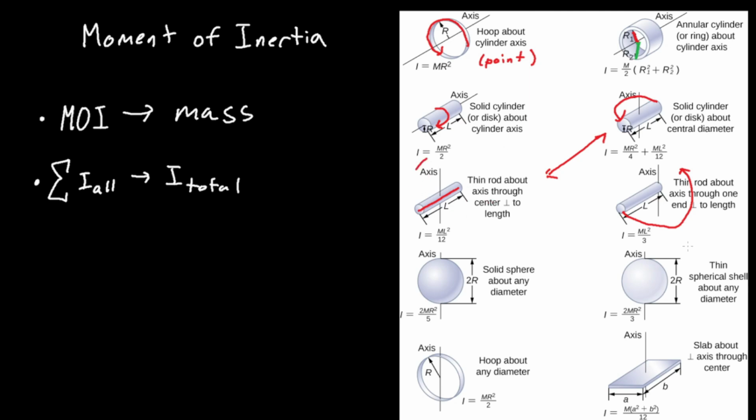And usually you're going to be using this one for very thin objects like sticks or super thin steel rods rotating. So it's honestly not too bad to differentiate them, especially if the problem doesn't give you a radius. If the problem doesn't give you a radius of your cylinder, then you know to use this guy right here.